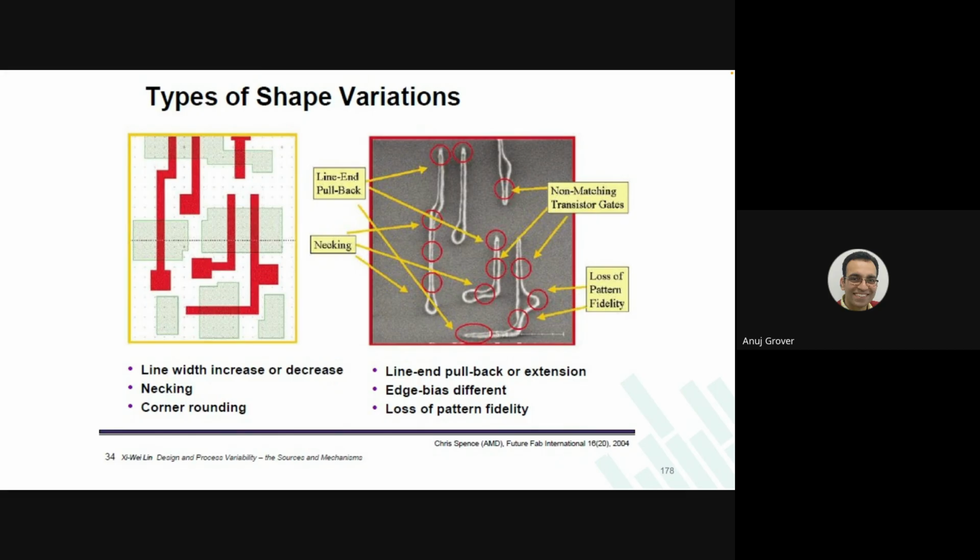In fact, what we do is we surround the entire memory array with a set of shadow rows, which are not accessed. They are not replica rows. They are just there to give the environment to the memory cells.